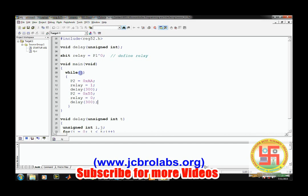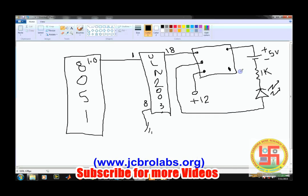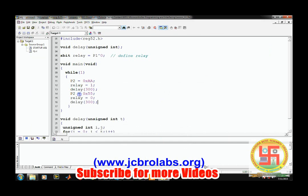As we have discussed, it is active low, so when we provide 1 to the relay input, the output is 0, and because the relay's other point is connected to 12 volt, we get 0 here, so it will be connected. So this is how we can simply turn our relay on or off. This is the simplest program. So let's now compile it and see if everything is fine.